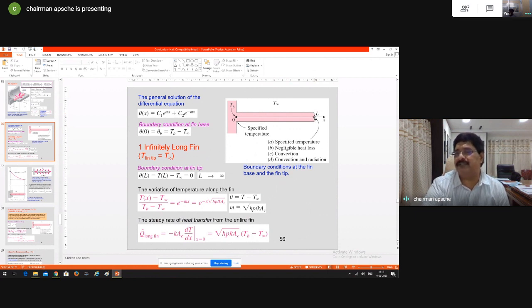This temperature is measured to be TL, meaning I know the temperature there. When someone is measuring the temperature and indicates that the temperature at the tip is TL, I take that as a boundary condition. Convection is still happening, but I take TL as the temperature, and assume that TL is not changing. Then my solution is quite simple because I have two definite boundary conditions.